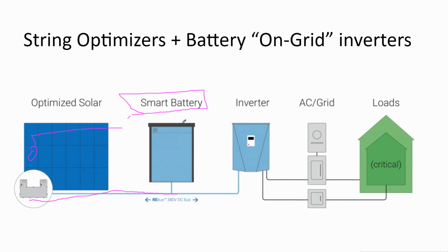And so what they've done is put their battery on a battery management system that also keeps that battery output voltage compatible with this 380 volt bus, and landed it on an inverter. So it's kind of like a SolarEdge system, except you can just click on additional batteries however you see fit and run the load.